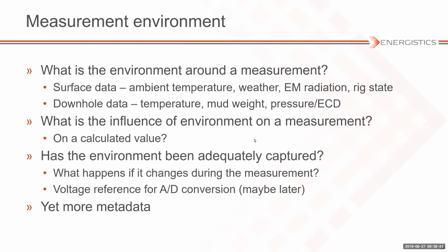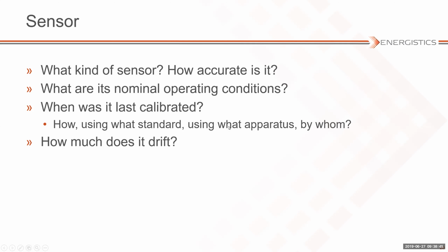So the last thing I want to talk about here is the sensor. What brand of sensor is it? How accurate was it when it was purchased? What does the catalog say its operating conditions are? Is it only good between 75 degrees Fahrenheit and 100 degrees Fahrenheit? Is it good when it's cold? Is it good when it's really hot? What does the catalog say? When was it last calibrated?